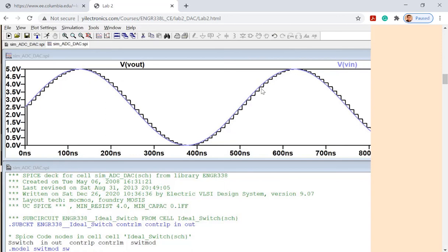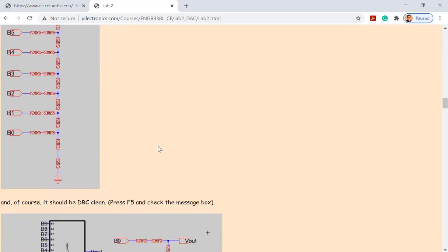And so what's the problem though? If you have a low pass filter involved, it can smooth out the signal, but however, what's going to happen? Slower response. So we got a time delay, and maybe a signal attenuation as well. So these are the issues with involving filters. But you can amplify the signal back to the normal range. But still, you are going to introduce time delay to the signal, right? Okay, so that's what you are going to do next Tuesday.